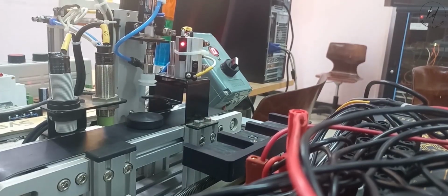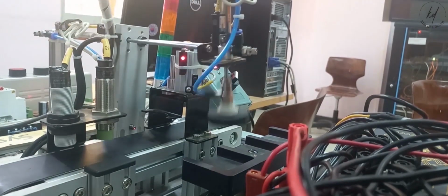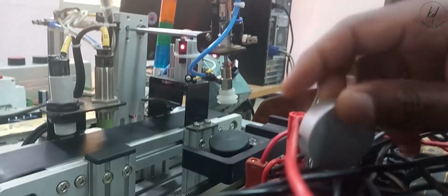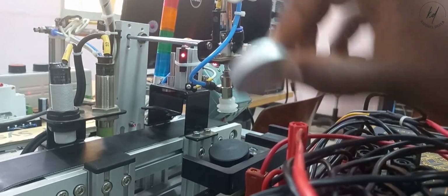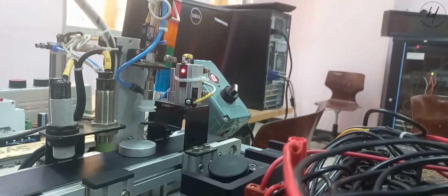Generally, this design is used in industries to do repetitive tasks, which reduces human effort and saves time. The basic mechanism includes gripping, lifting, moving, placing, and releasing the objects at desired locations. And when any object is brought in front of the sensor, the X-axis cylinder retracts and is initialized for the next task.